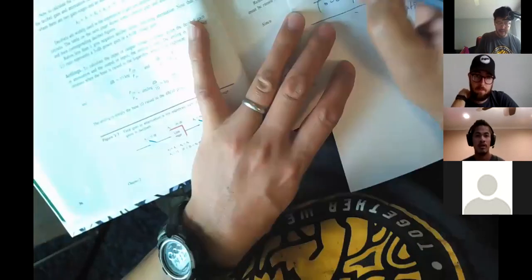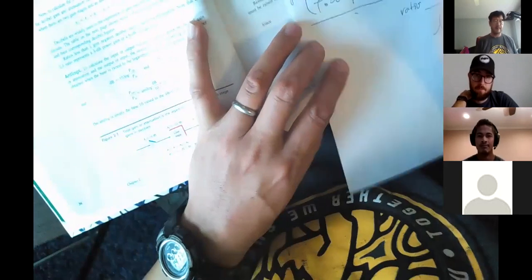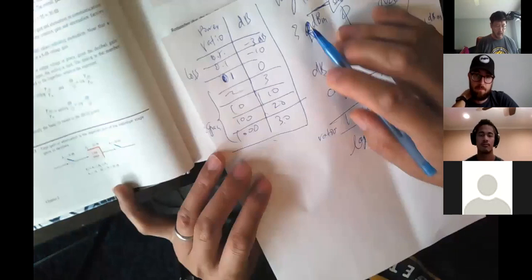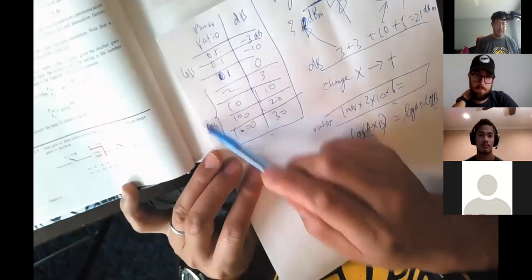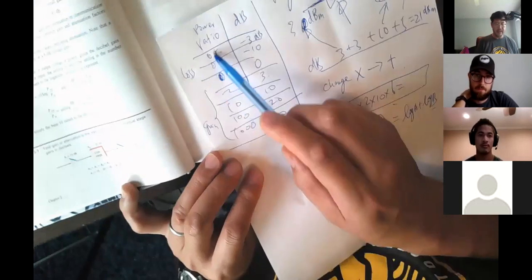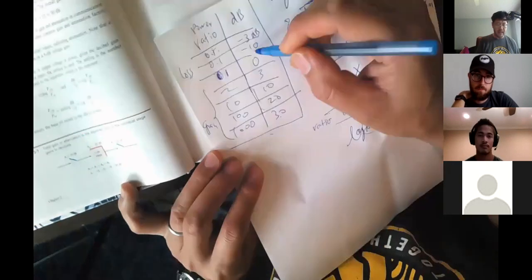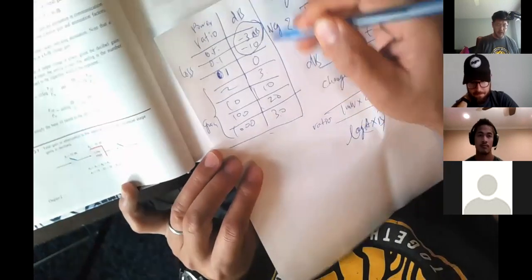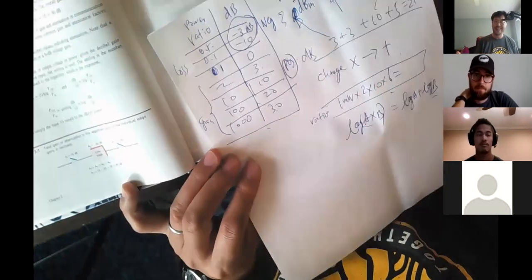This is a gain. This is loss. So when the gain is larger than 1 or equal to 1, we call it gain. When it's smaller than 1 in ratio format, we call it loss. We found out all the loss are negatives. So negative dB means loss. Positive means gain. So that's another thing.